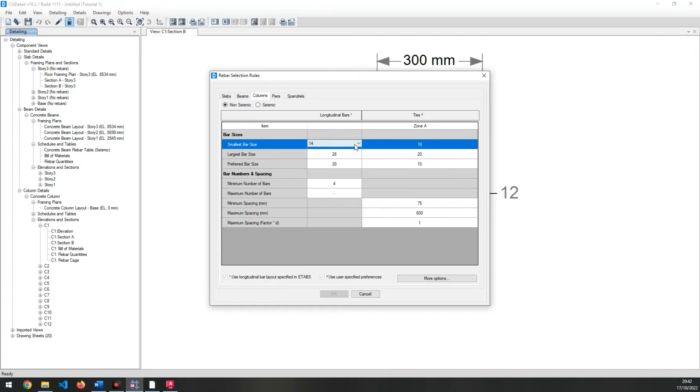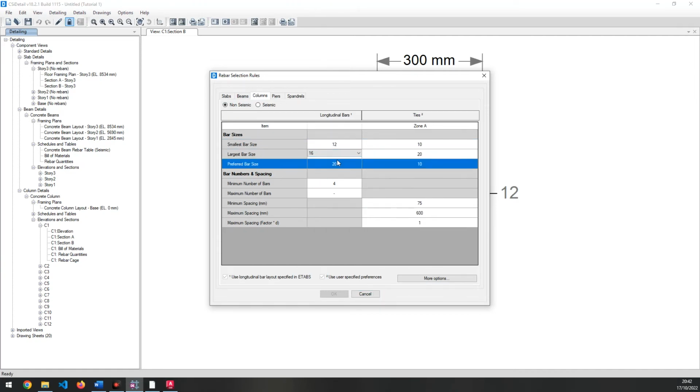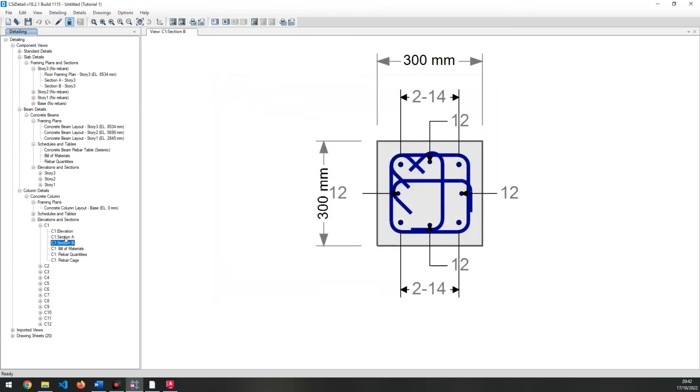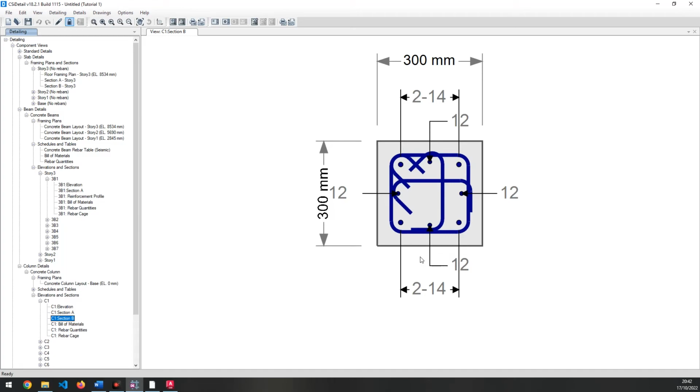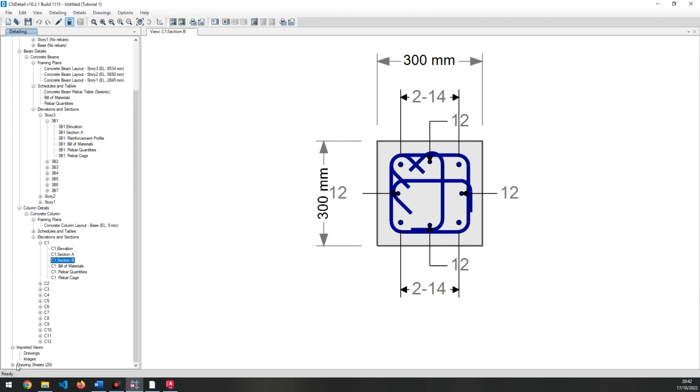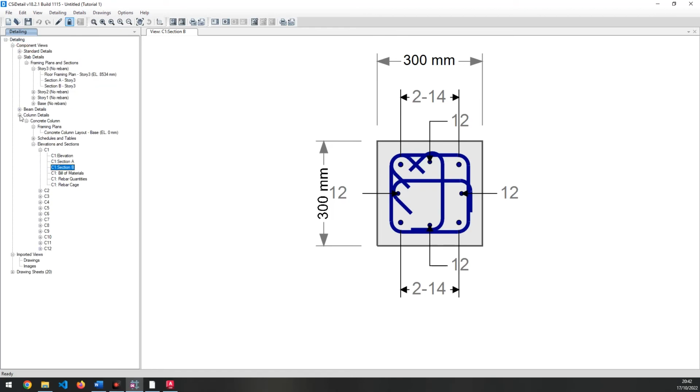So here you can see, so you can check by just selecting here. So click on OK. For now it's grayed out because we haven't unlocked the model. So in this way you can see this and check everything, and you can make correction. So here instead of 2 numbers of 14 dia in each corner, we can go with this 16. So once everything is checked,